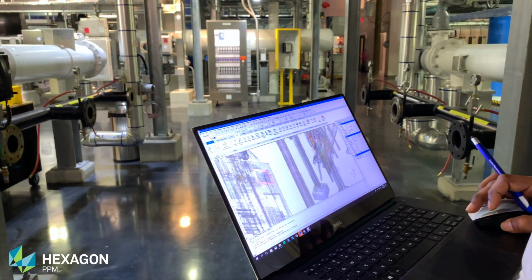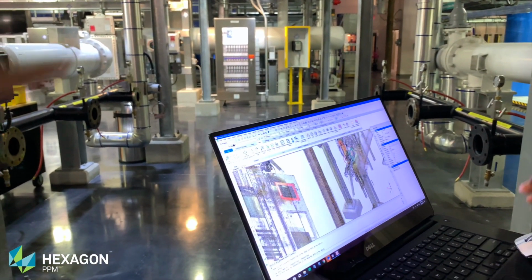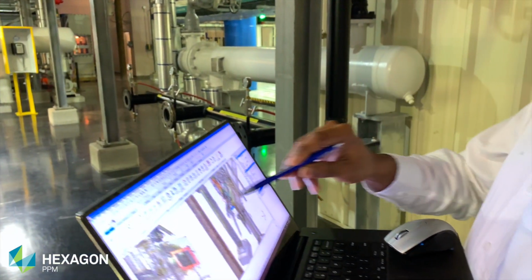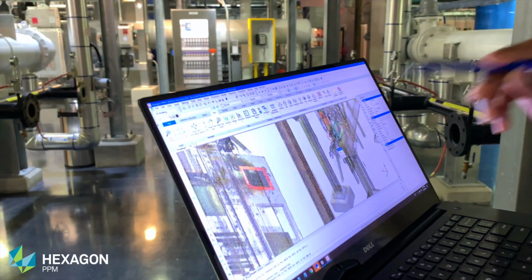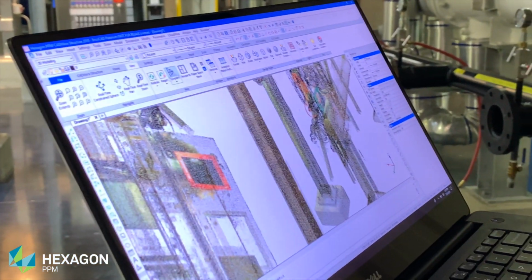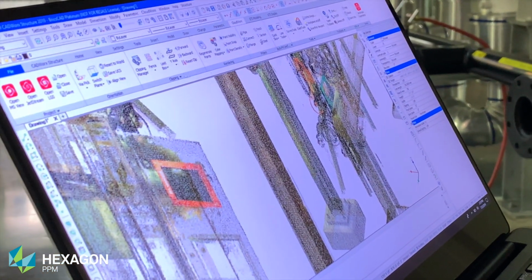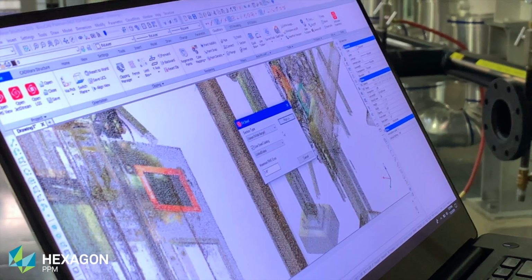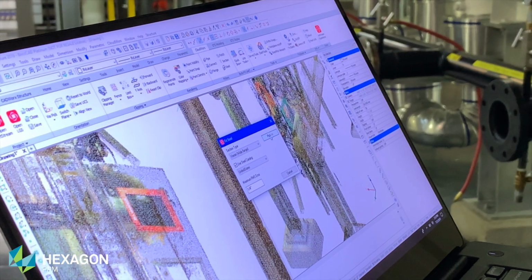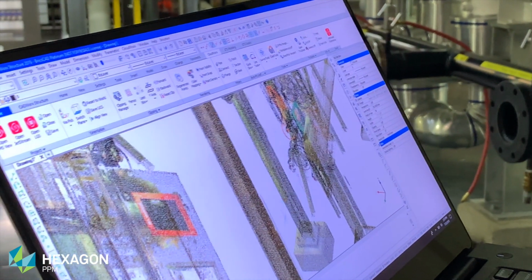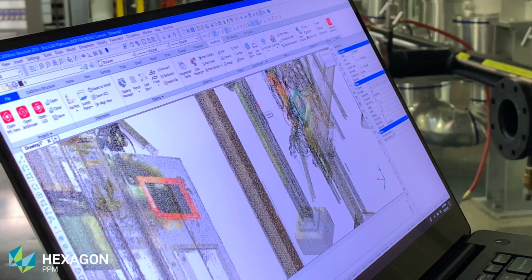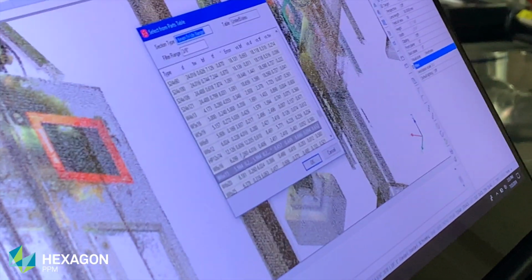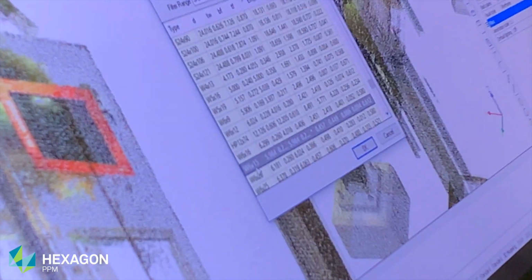So this whole area you scanned, right? Yes, absolutely. And that's the first column that we're looking at. Let's say we want to know what shape it is. I'm just going to go to this shape fitter tool that we have. I'm going to use the US section shapes and pick 2 points on this shape, and you can see that it comes up with 6 by 15.